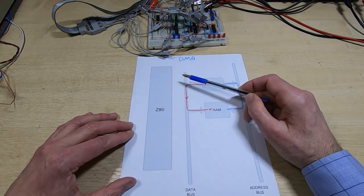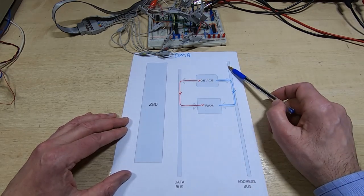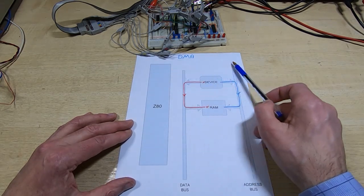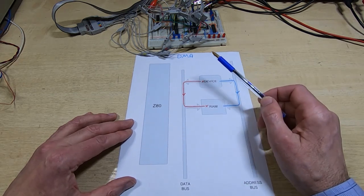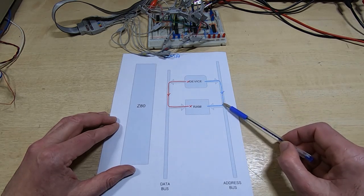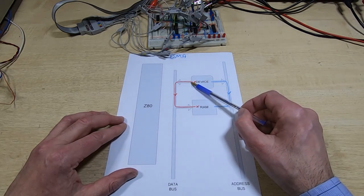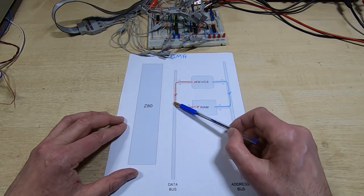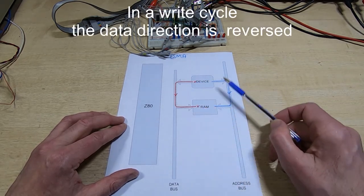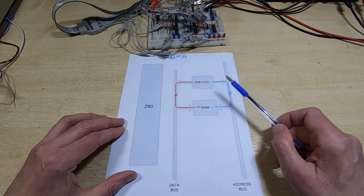In DMA mode, the Z80 effectively releases control of the data bus and the address bus, so it goes into tri-state as far as the connection to these buses and several control lines is concerned, and then the device itself is responsible for providing the required address to RAM, and then it is also responsible for transferring the data through the data bus into the required RAM address. So you can see a very efficient single step process, and it seems like it's a no-brainer.